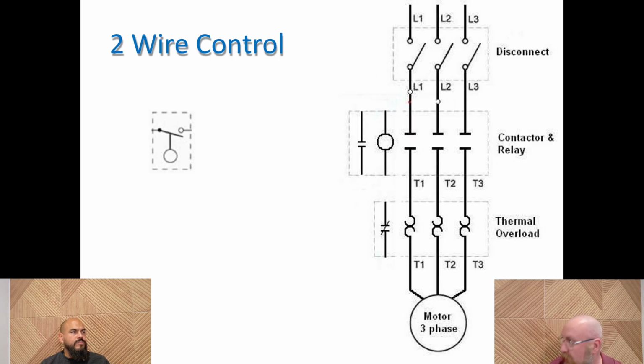If you lose power, right? If all of a sudden the power goes out in the building, your motor stops, and then you're looking around for a flashlight and whatnot, and you're leaving stuff in strange places, it causes chaos. What happens when the power comes back on? Well, that motor goes straight on. And so using this for things like saws and other forms of heavy machinery that can injure people, not a great idea.